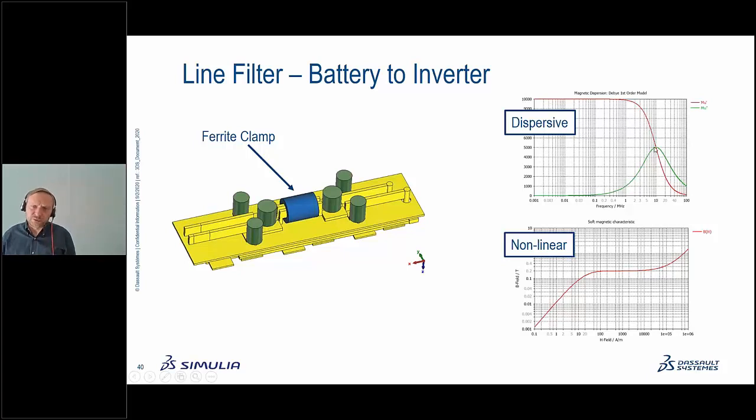It's a pretty high frequency, but typically a ferrite will have this tipping point somewhere between 10 megahertz maybe to 1 megahertz or to 500 kilohertz. So this curve is moving depending on the ferrite material itself, and you will have some losses. This is typically a curve which we can easily incorporate into our 3D simulation. So including the dispersion of a material is not a big issue inside Microwave Studio.